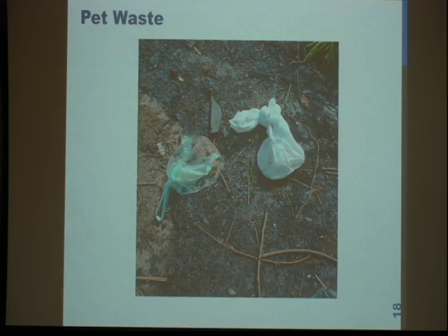So I have a bunch of pictures of things that we see around town to look out for. Pet waste, that's the big one. A lot of people walk their dogs every day and pick up the waste with a baggie. And then some people will walk their dog every day and dump it in the same catch basin every day. By the time we get around to it, during our catch basin cleaning program, the whole thing is full. If you ever Google it, there are cities and towns whose whole downtown was flooded because of dog waste being dumped. I think it was in Canton, someone dumping their dog waste clogged the entire system. So we tell people that it has to go into the trash.